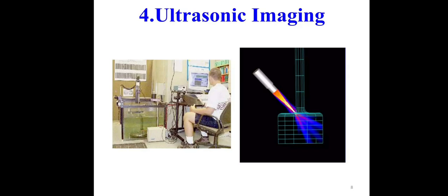Ultrasonic testing. Ultrasonic testing is one of the popular non-destructive testing methods that uses sound energy to determine the integrity of the testing objects. In ultrasonic testing, very short range, high frequency ultrasonic waves, whose range lies between 0.5 to 20 MHz, are used for detection of surface and subsurface flaws in the testing objects.